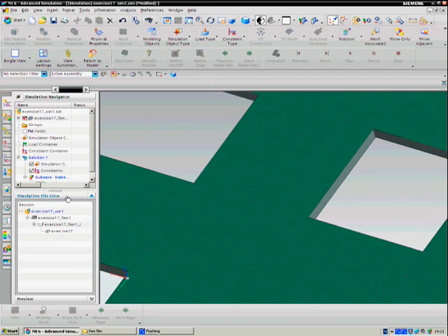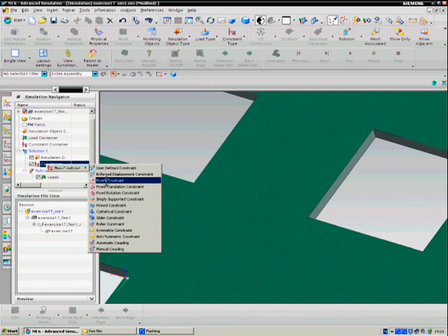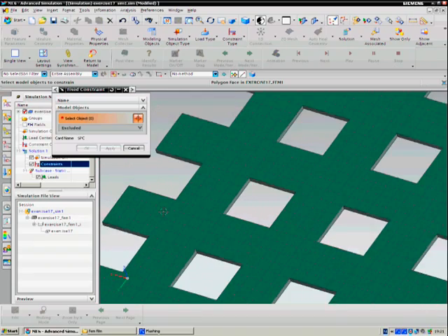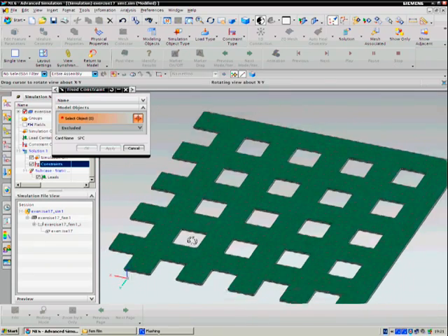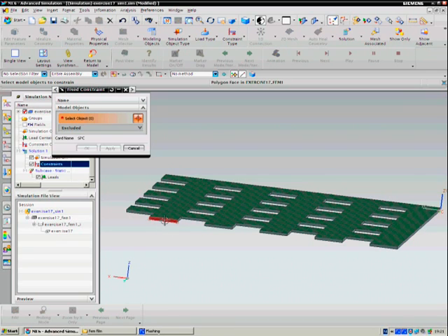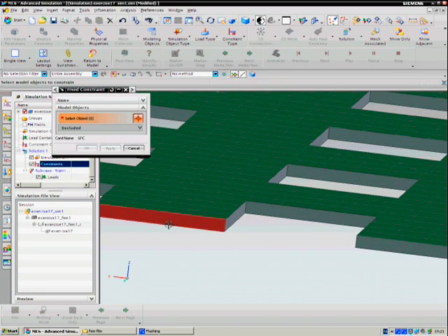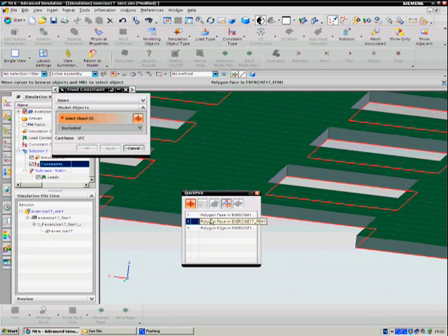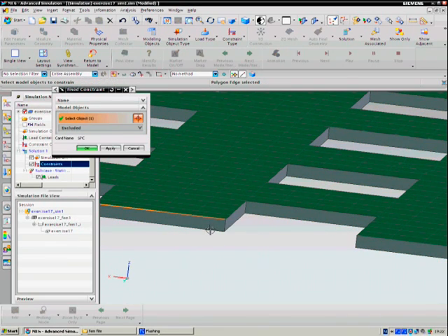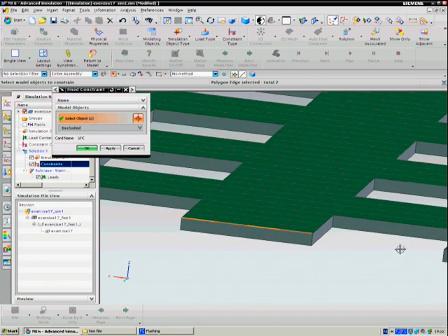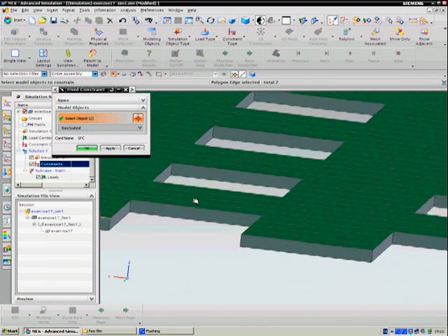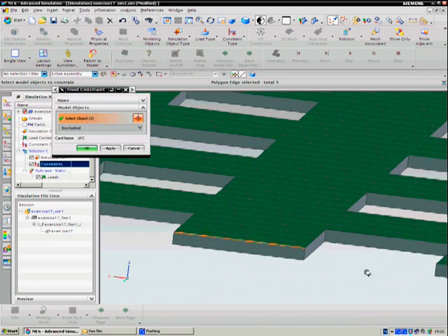If you have created the mesh and the material properties and the thickness, you can start by adding loads and constraints. We choose to apply a fixed constraint on the edge of the model, and notice that you're only allowed to apply constraints and forces on the mesh itself. You're not allowed to place it anywhere outside the mesh anymore, otherwise you will create an error.